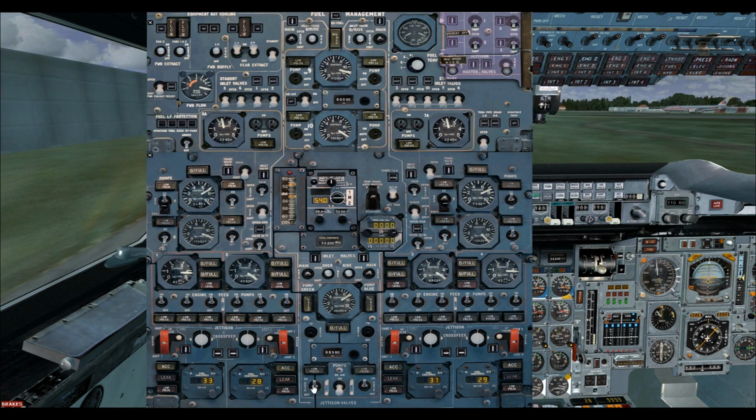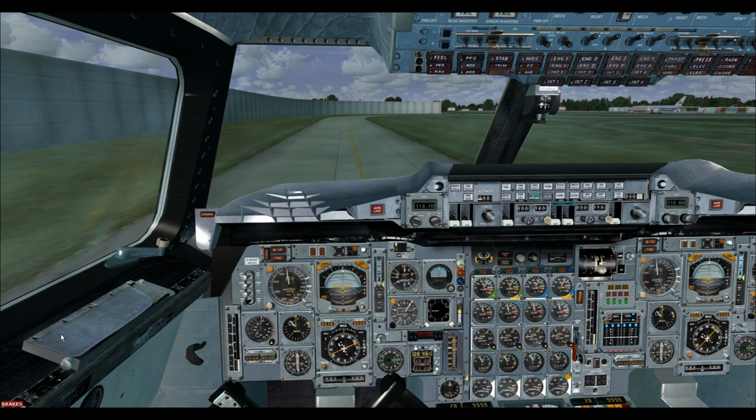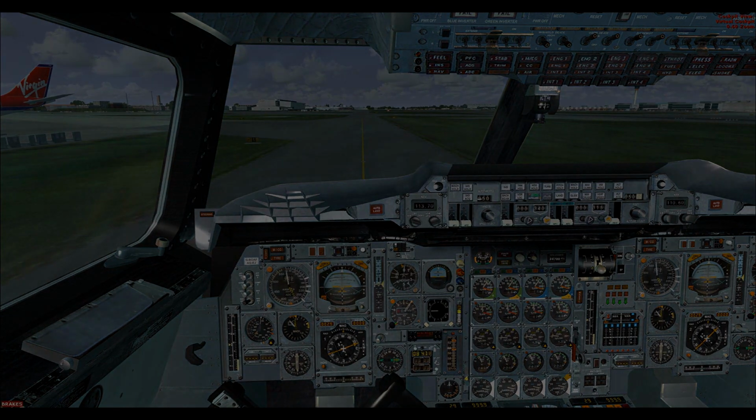We will close the inlets. We'll close the pumps. And now we'll turn on our normal pumps, the right-hand pumps on tank 5 and tank 6 for de-air, and the left-hand pump on tank 7. The left-hand on 8 is off anyway. And we can see that we've achieved 54%. And we're all set now, ready for our departure with the correct takeoff center of gravity.